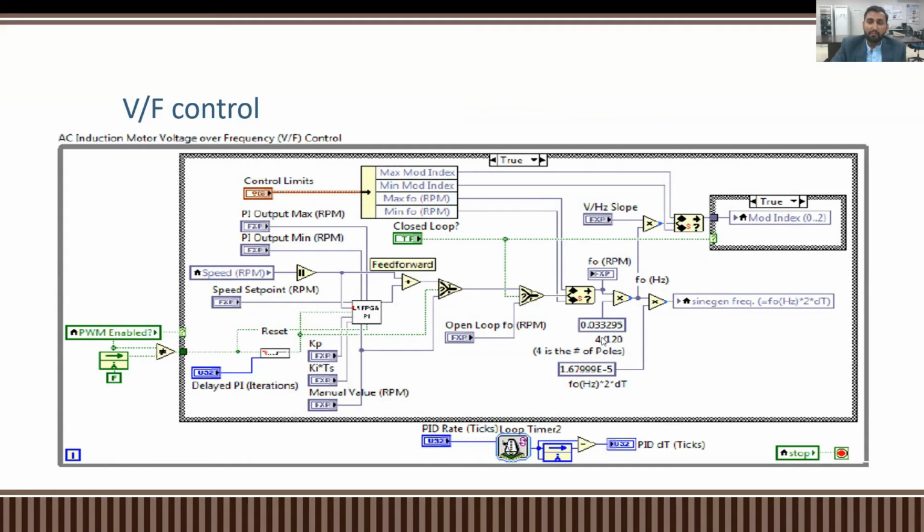For that reason, the output speed is given at the input, that is here. That speed we will give to the induction motor as the input, then the PWM will adjust the frequency and voltage accordingly to the output speed. Here is the formula, N is equal to 120 F upon P. But in this scenario, we are giving speed as input and we are calculating the frequency as output.